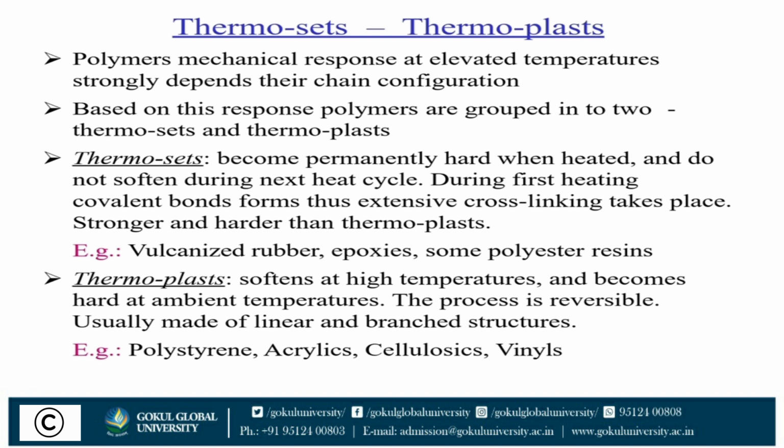The two types of plastic are thermoplastic and thermosetting plastic. Thermosetting plastics are those formed into shape under heat and pressure, resulting in a permanently hard product. The heat first softens the material, but when additional heat and pressure are applied, it becomes hard by a chemical change. Phenol formaldehyde (Bakelite) is an example of a thermosetting plastic.